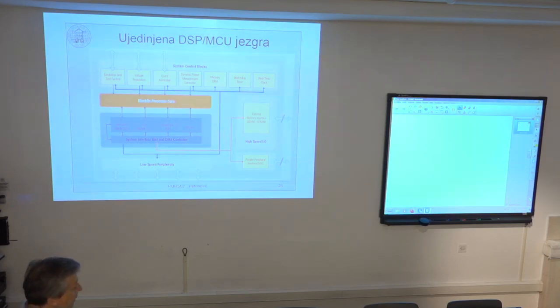less efficient, especially if the access is random. So if you go to this address, to that address, to that address, if the access is random, then each of these accesses requires maybe 10 cycles just to be able to fetch this data from the desired address. But if you do sequential read, it can be done in a much more efficient way.